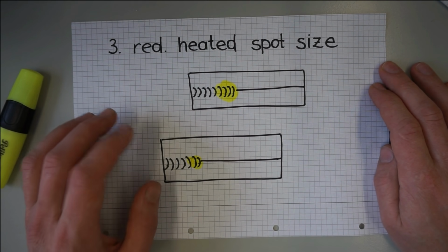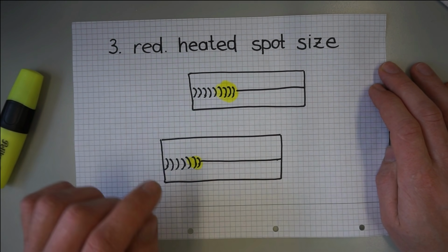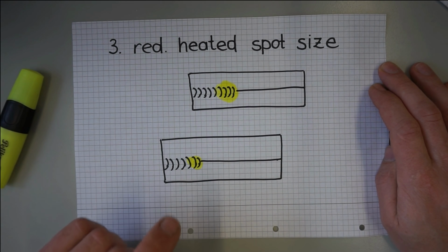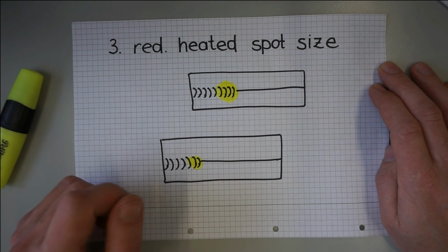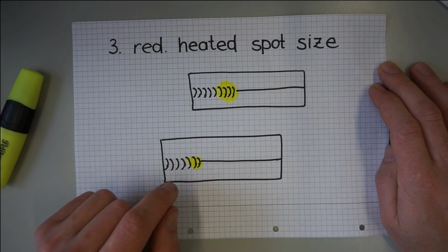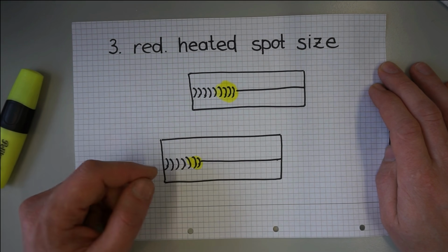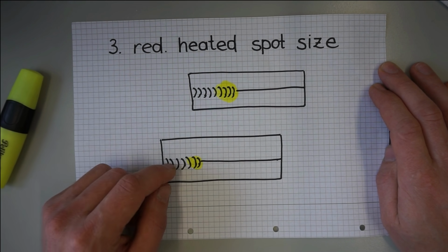But all these neat methods of reducing heated spot size have a natural limit. The smaller the heated spot, the more intense our workpiece is strained in the heated zone. In engineering terms, the temperature and strain gradients increase. With soft and ductile materials, this may be of no consequence, but the high strength or the brittle materials may suffer from local embrittlement or even from local cracking.